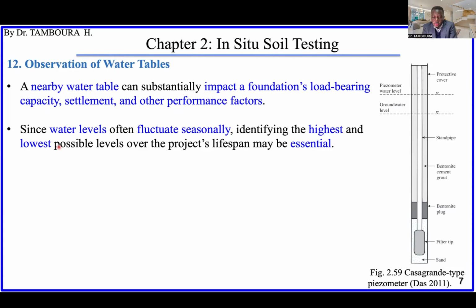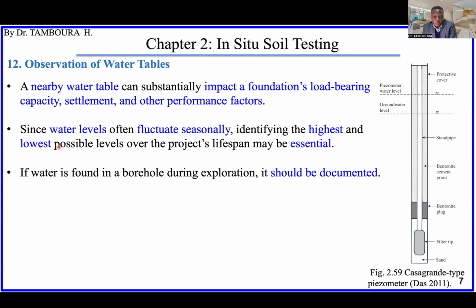It's very important. If water is found in the borehole during exploration, it should be documented. So during the exploration, if you find water, you need to note it and write it in the report.